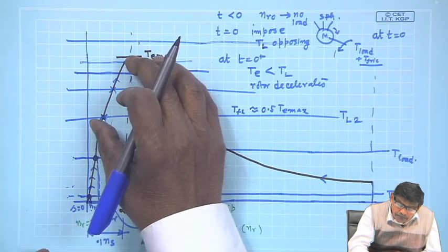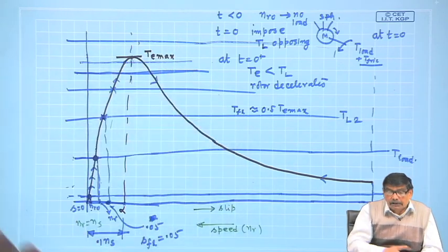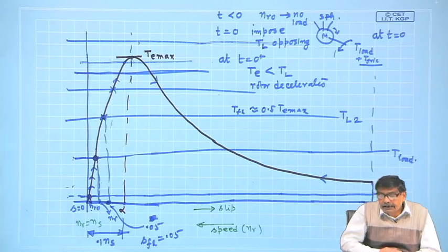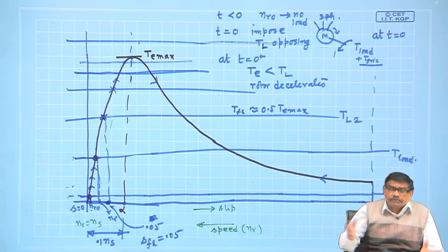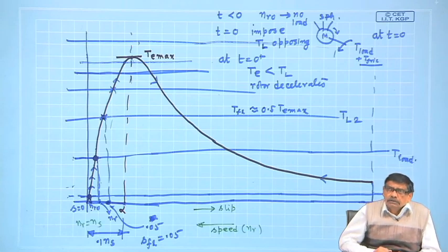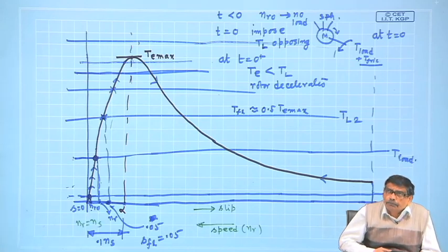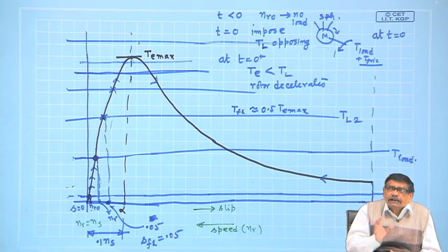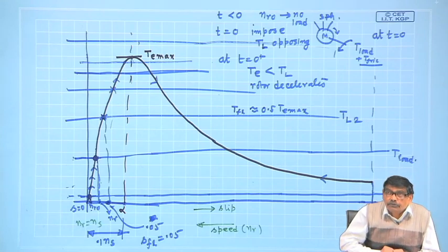is equal to say 0.05. Then you have enough margin, because always remember that any electrical motor can be run overloaded for some time, is it not? It is not that you overload the machine and the machine will burn. 15-20% overloads are possible, but for a definite amount of time. Continuously do not run a motor overloaded.